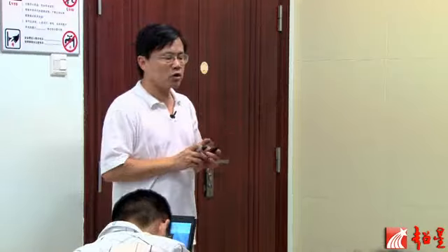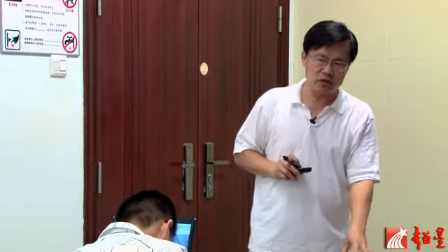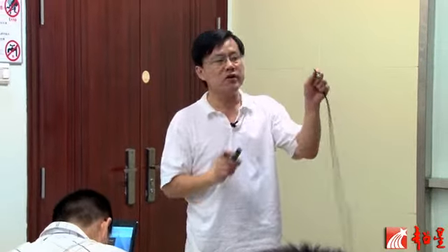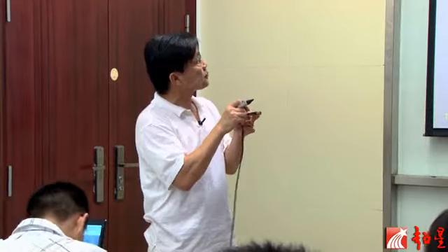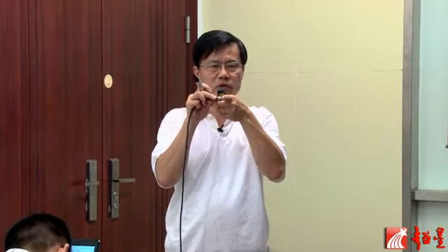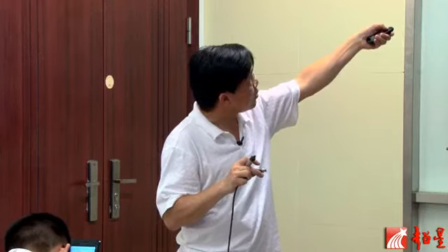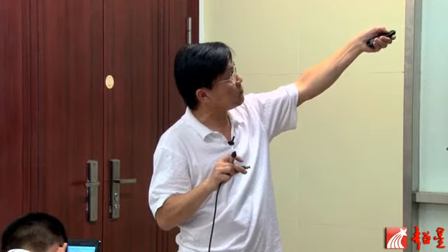The transmission line model we're dealing with is a very specific transmission line. Okay, like this. This is a very nice transmission line. The wave propagated through this is called transverse electromagnetic wave. That is, the E field is in one direction, H field is in another direction. They are perpendicular from each other. Their dot product is 0. And then the energy or power density with pointing vector is in the other direction.